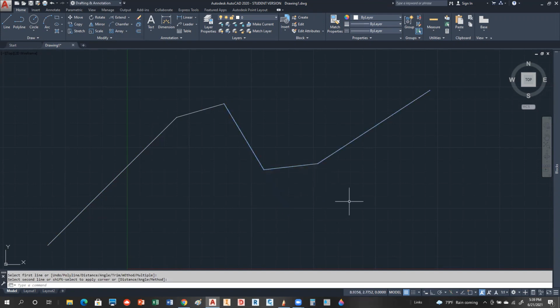So if you want to trim or extend, both variables, distance 1 and distance 2, would have to be set to zeros. And then at that point, you can do the extend or trim. I think if you're going to do that, I would use fillet because fillet's a whole lot easier to use. That's my opinion. Okay. Any questions on fillet? I'm sorry, chamfer.